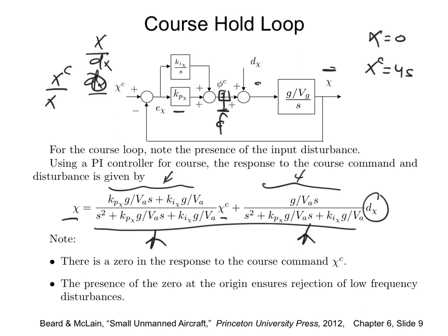The frequency of your outer loop, inner loop. This is where the DC gain comes in. So you are immediately getting a commanded roll angle, from phi to phi commanded. Phi becomes phi commanded immediately, looking from the speed of the course loop. So for the course loop, the input is commanded course and the output is course, and there are two transfer functions here. One is from commanded course angle to course, which is this.